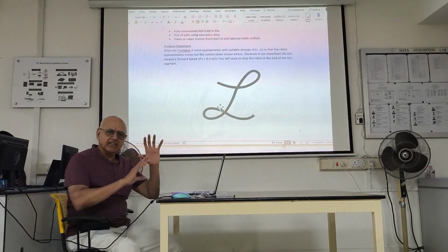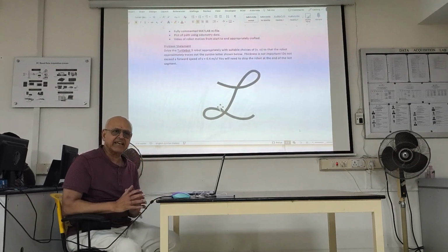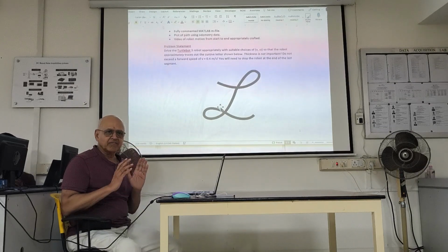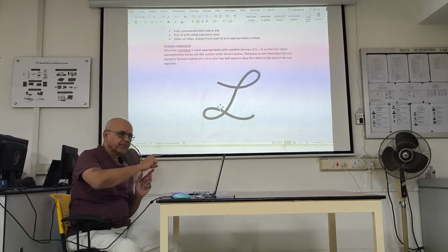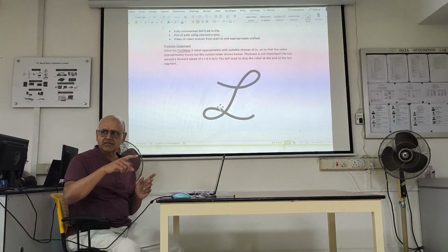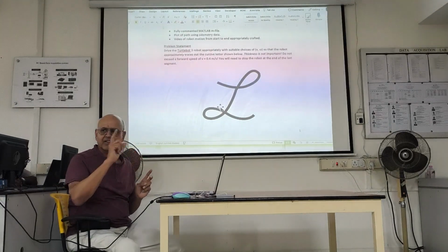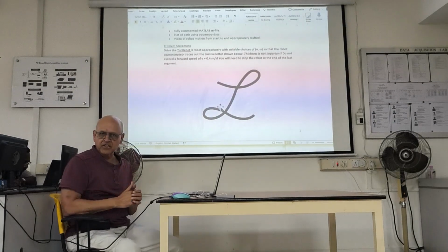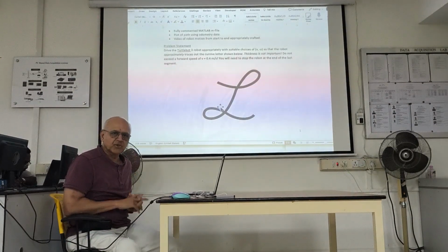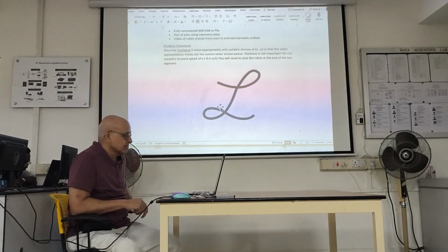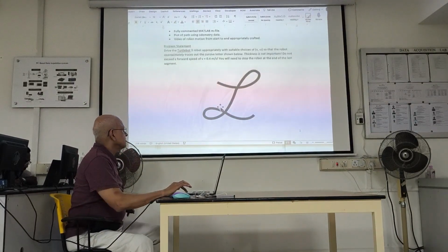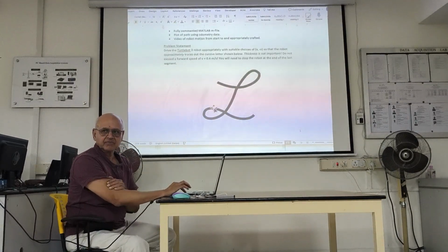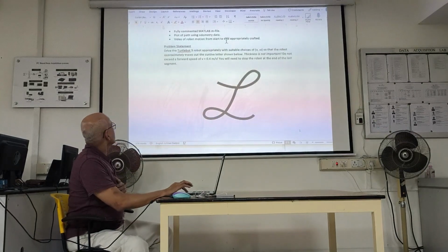Now you are correct in a general sense, but in robotics, the radii can be negative. It means that you're going counterclockwise around a circle. I'm sorry, clockwise around a circle, R is negative. If you're going counterclockwise, R is positive. That is the robotics convention. So you can have R negative. Any questions? Okay, so I'm going to shut this down. I'll finish this up tonight and post it.